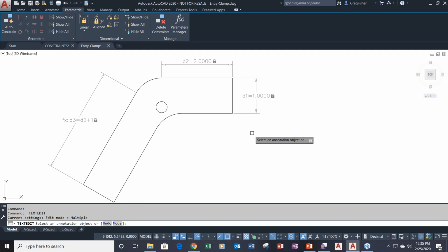That's what you're not going to have without constraints. That would not change any geometry, as we all know. If it's regular AutoCAD and your dimension's wrong, it's time to fix the geometry. Here, I can adjust the geometry based off of what I plug in for the dimension. I'm going to hit escape to get out of the edit text or edit dimension, if you will.